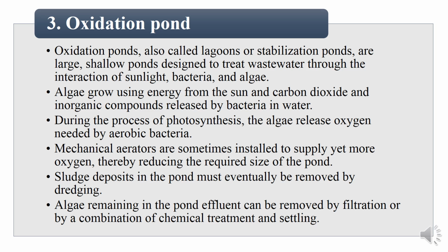Third mechanism of the secondary treatment is the oxidation pond. Oxidation ponds, also called lagoons or stabilization ponds, are large, shallow ponds designed to treat wastewater through the interaction of sunlight, bacteria, and algae. Algae grow using energy from the sun and carbon dioxide and inorganic compounds released by bacteria in water. During the process of photosynthesis, the algae release oxygen needed by aerobic bacteria.